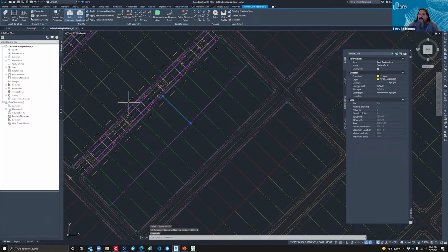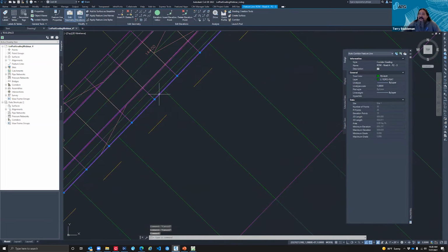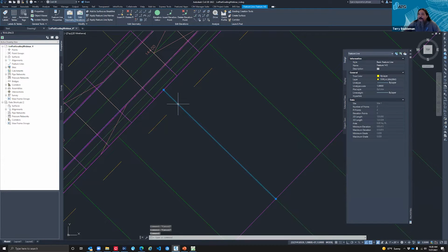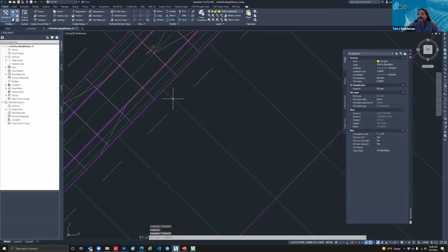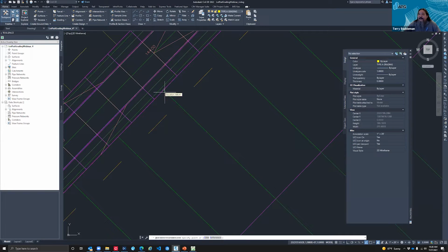One thing that I want to bring up is feature line style hierarchy. So I extracted this line out of the corridor. If my hierarchy would have had this style, which is basic, higher than my corridor style, it would have changed the elevation at this point to 0, because I just created my feature lines. I didn't assign any values or elevations to them, and we noticed that it's set to 806. So it's taken the feature line from our corridor and assigned it to our lot line.